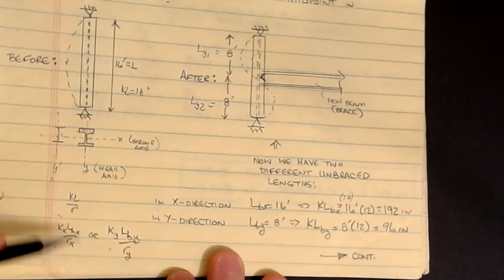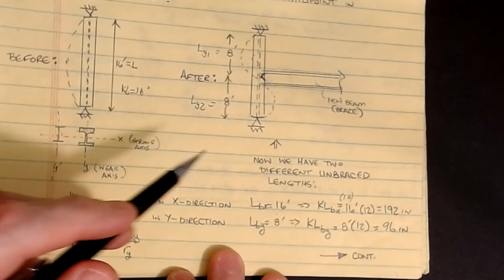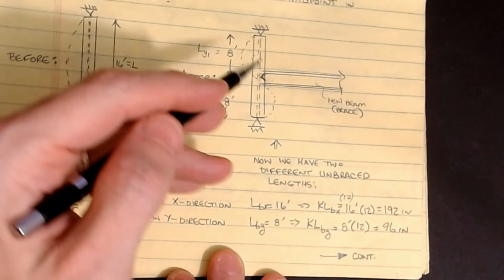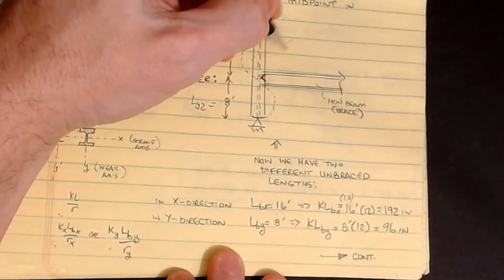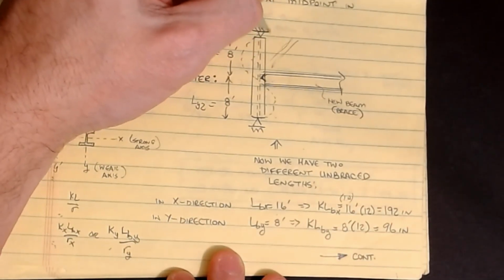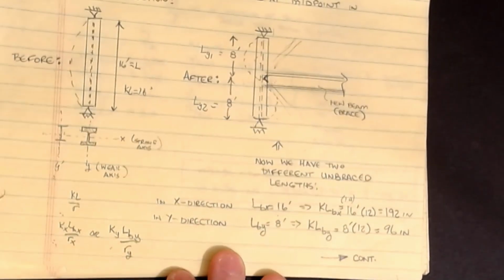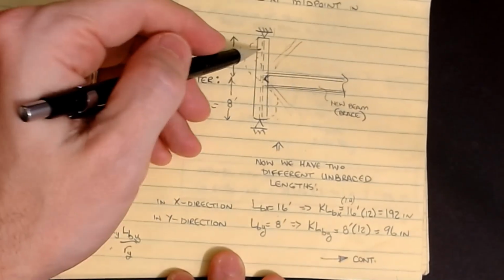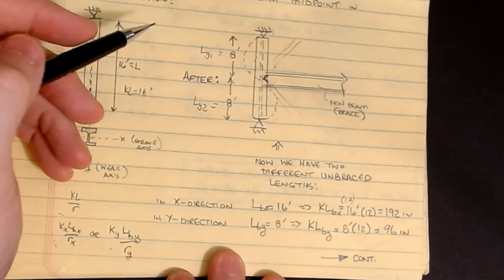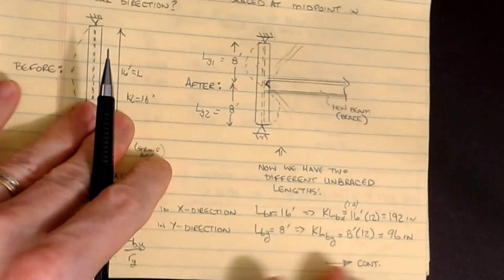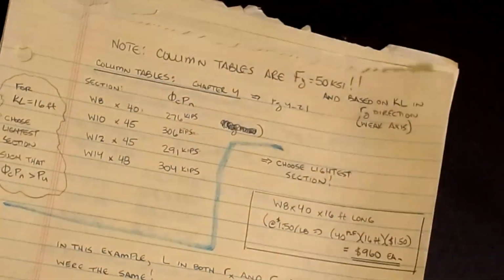Because it's a common problem that occurs, we provide bracing, whether it's a beam from another floor coming in and bracing the column, or maybe some sort of kicker coming down from a beam to help brace that column, a K-brace or chevron brace kind of arrangement. All of those can be used to help protect this column and to keep that point from moving. All are valid techniques. So this is a common occurrence that we're looking at, and this is how we handle it.